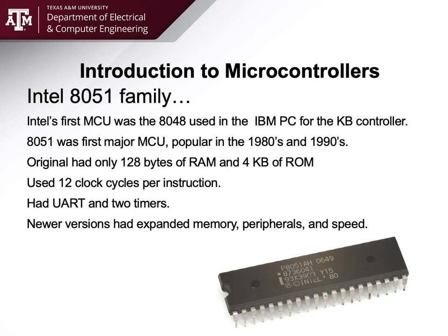All these keys had to be monitored, and to know which key was pressed, they used another processor, a dedicated microcontroller in this case, the 8048, to monitor the matrix of rows and columns to determine which switch was pressed, and tell the main processor, the Intel 8088, that yes, the letter Q was pressed, or the enter key was pressed, or the number one key was pressed.